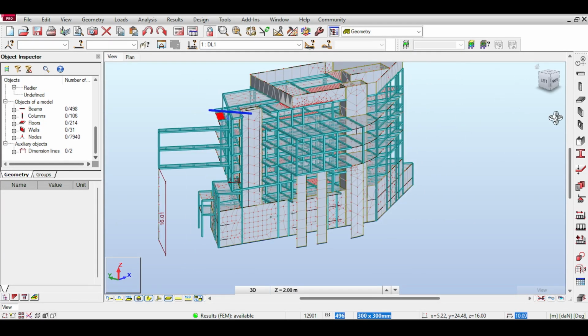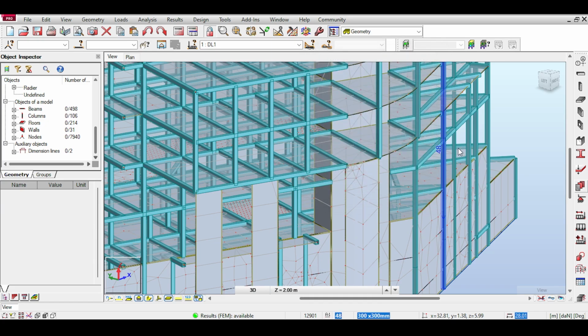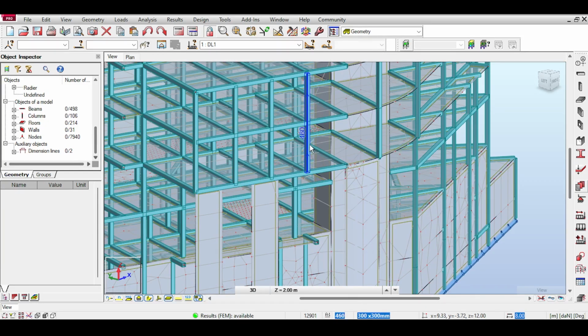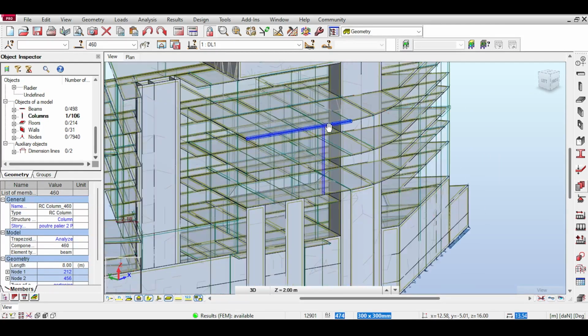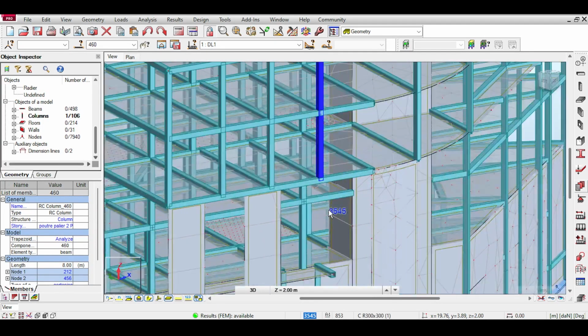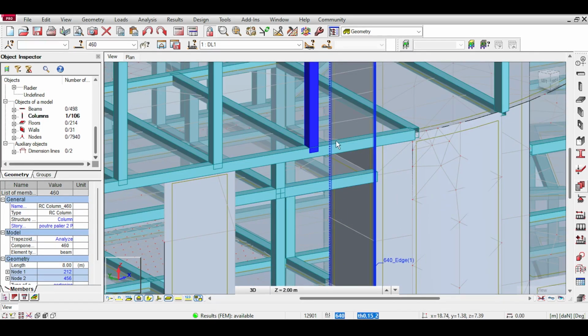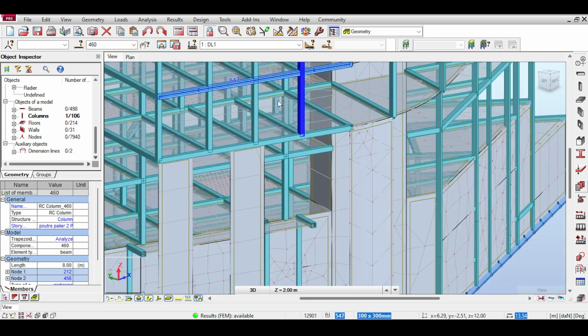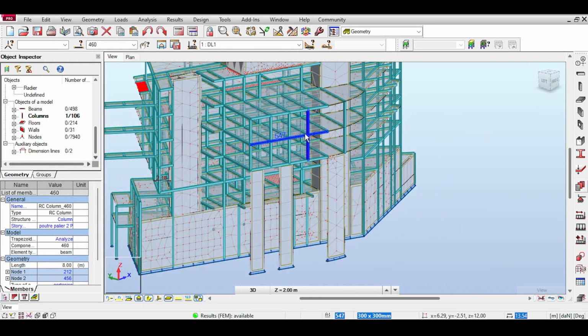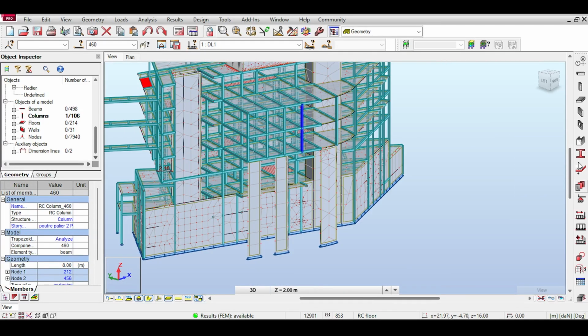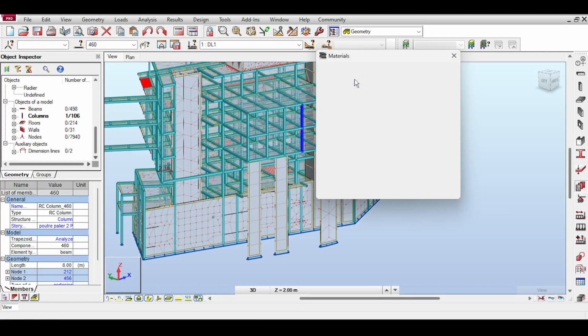I continue our section checks and check the material very quickly. I want to know exactly what he used. So are his material assumptions okay? Now, to be honest, I don't know exactly what available materials he has in his place. Well, that's another cantilever that needs to be strengthened because it's a column that is discontinuous. You see, look, whenever you have a column that is discontinuous, the beam that carries the column needs to be big. Let's check out the materials, have a look.